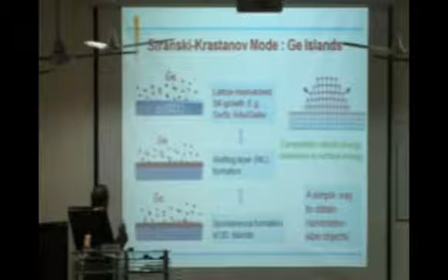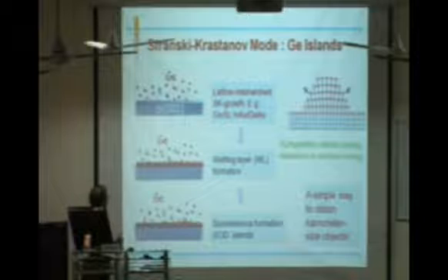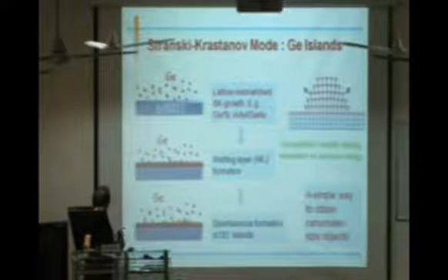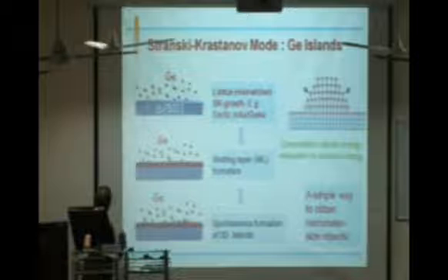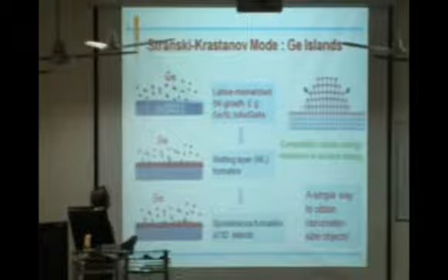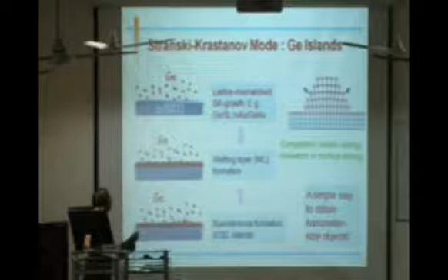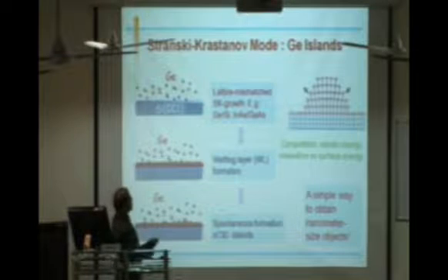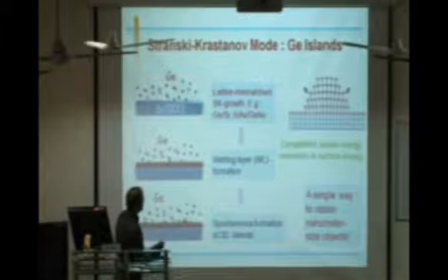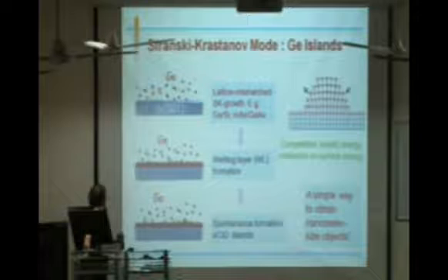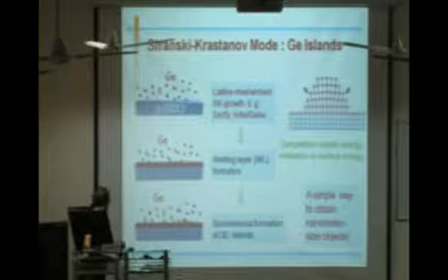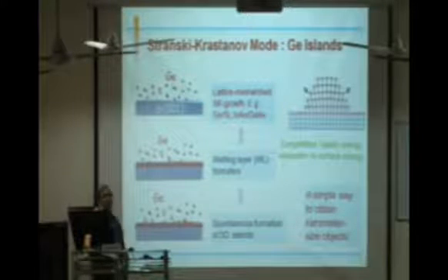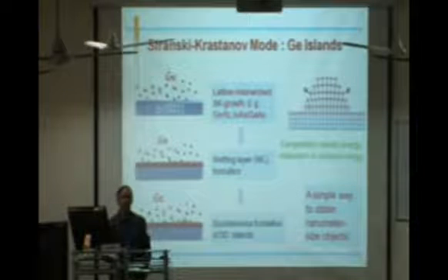In this case we have taken a system of germanium on silicon. There are many other systems like indium arsenide and gallium arsenide. If you put germanium on silicon, initially it will spread into 2 dimensions. But as you grow the lattice mismatched material, a lot of strain energy builds up. There is a competition between the elastic energy and the surface energy, and finally this gives free energy such that thermodynamically they will be stable if they make this kind of pyramids or dot kind of structures.